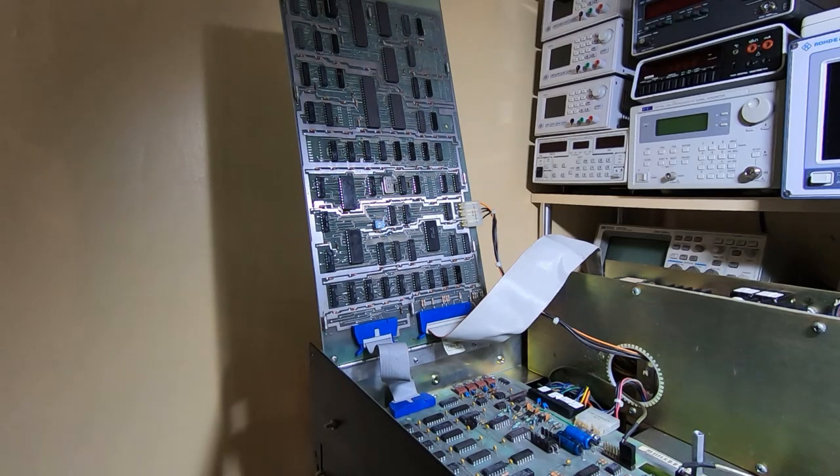The RX211 talks to this CPU card. You can see the large ribbon cable coming in, and then that interfaces with the interface electronics on the RX02, and then you have the actual drives themselves. And of course the fault could be anywhere in this chain. It could also be a fault with the floppy disks themselves. So it's a question of where to start when you get a problem like this.